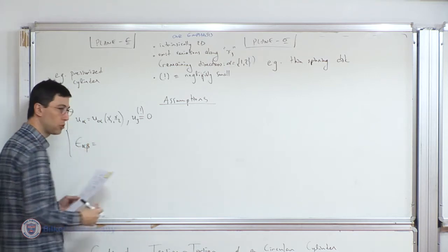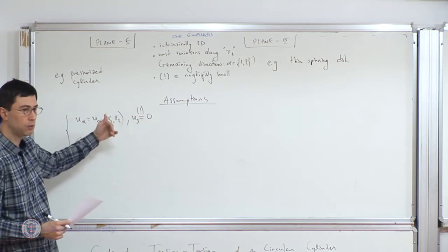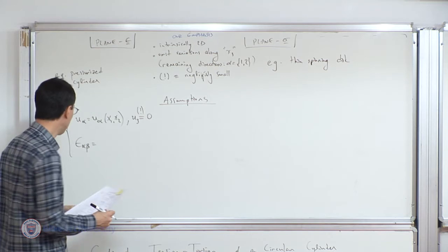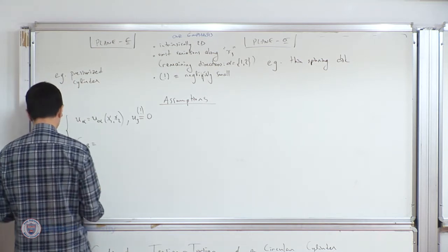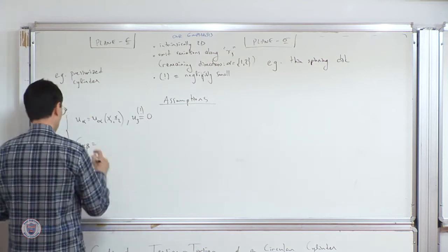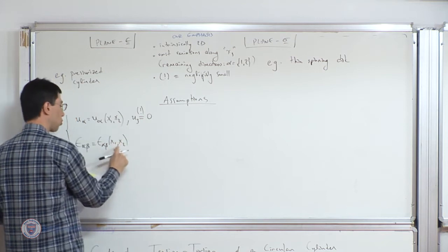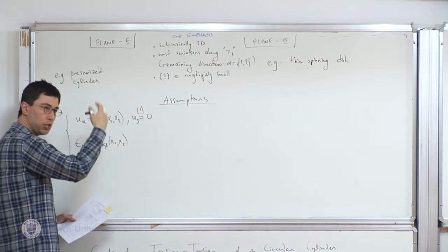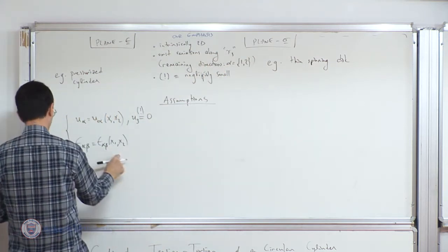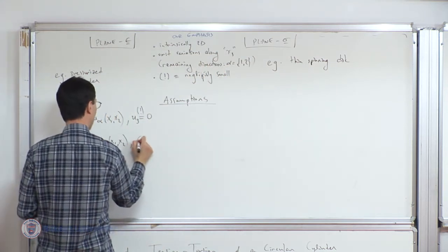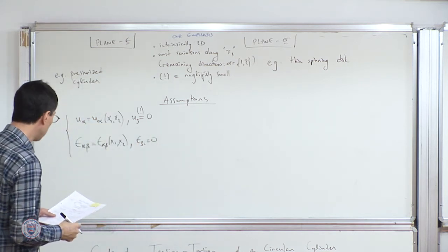Then we will have strain components. In a plane strain problem, u3 is 0, which means epsilon 3, anything will be 0. And all that remains is epsilon alpha beta: 1, 2, 2, 1, 1, 1, and 2, 2. All of these will always be a function of x1 and x2 only, because variations along the x3 direction are omitted. So these are non-zero, and epsilon 3, anything is equal to 0.